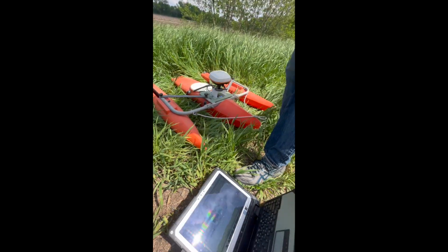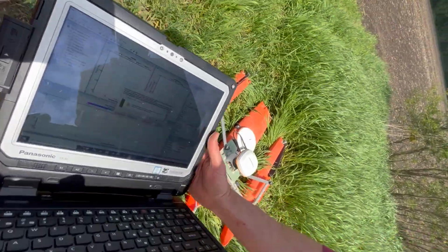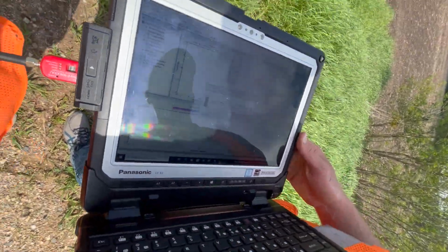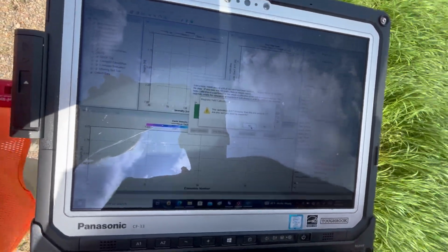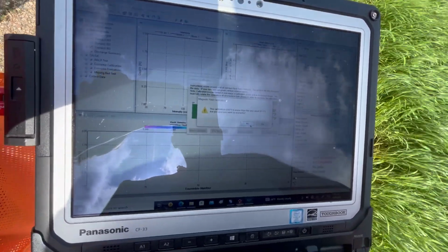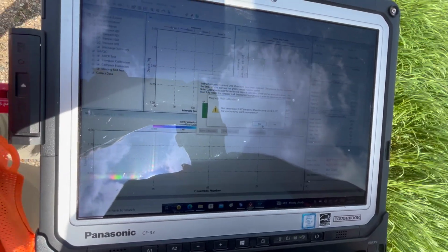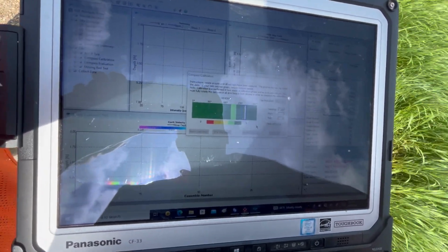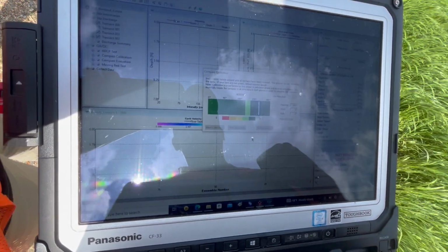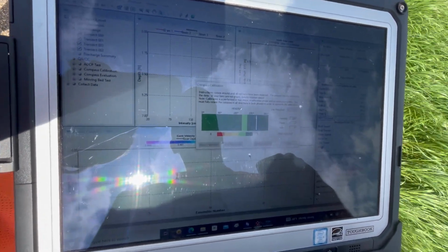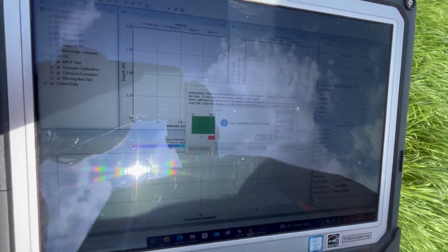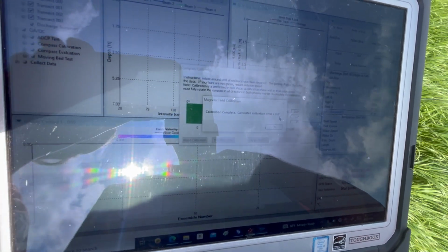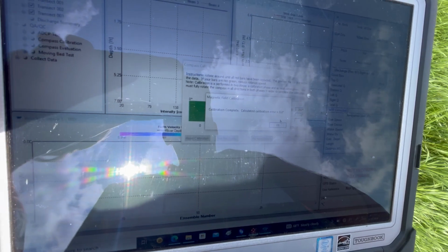Now it's processing it. The process for this is the same for the River Ray as the StreamPro. Here it's saying that our calibration is worse than the previous calibration, but we will accept it because this is a different location. Now it's going to apply it. It's been loaded. It should give us the error is 0.8, which we want. Anything under 2 is acceptable.